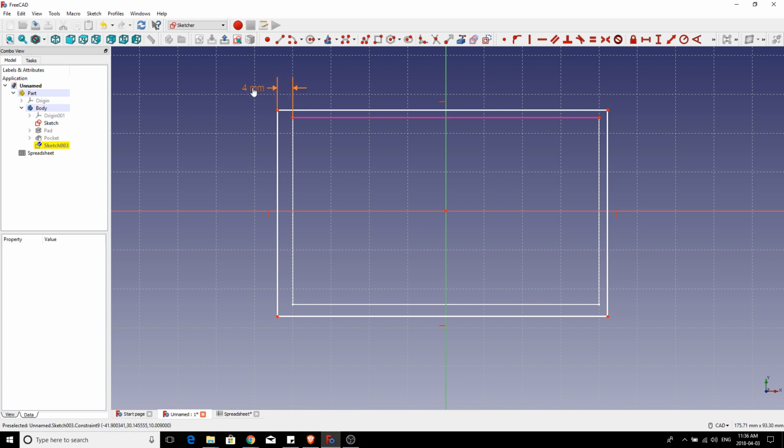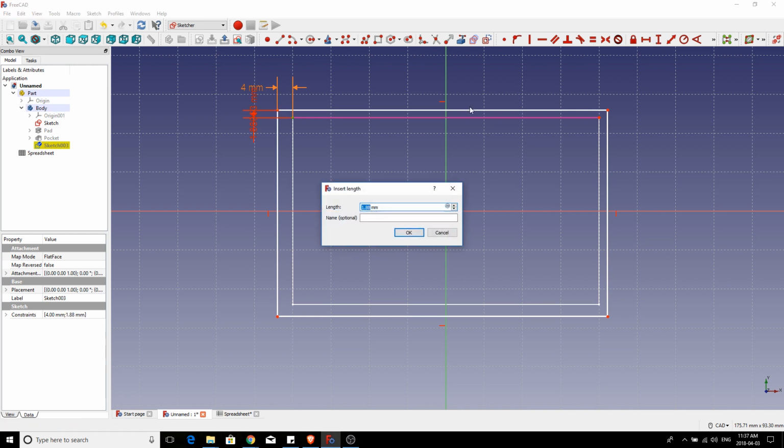Let's grab this and pull it out. And so it's saying basically from the edge of the card, we're going to be making a cut into our wall at precisely 4 millimeters. Awesome. Let's do the same thing for the vertical. So you can see there's a little bit of repetition in this, but you can't get sloppy. It's really easy to lose control of this stuff. If you just take your time and you're precise with it, you'll have no problem.